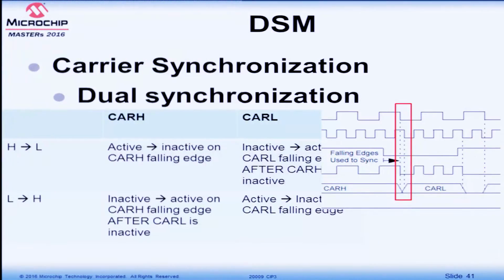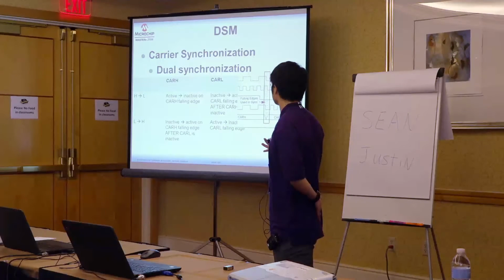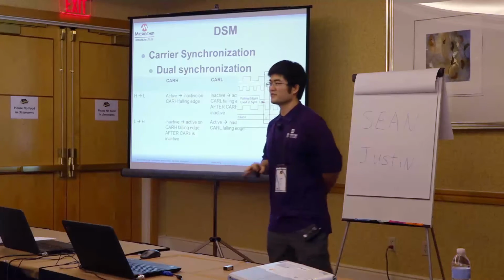The same setup: high, low, modulating, and output. My transition happens here. I'm transitioning from high to low. So the first thing that should happen is the following edge of my high side. After this happens, I'm waiting for the following edge on my low side. After I see those, okay, I'm good. I've finished all the transition. Now it's going to follow whatever is on the low side. Make sense?